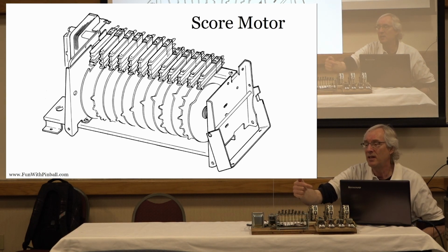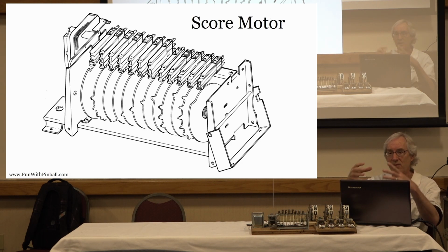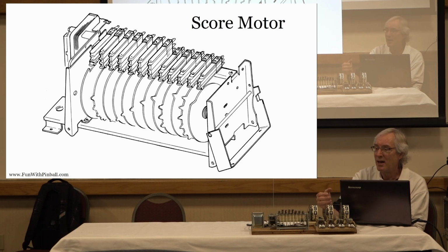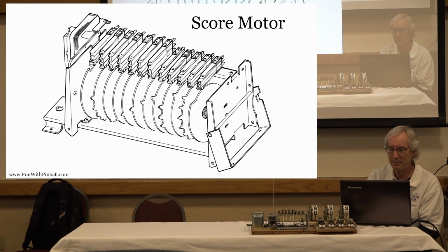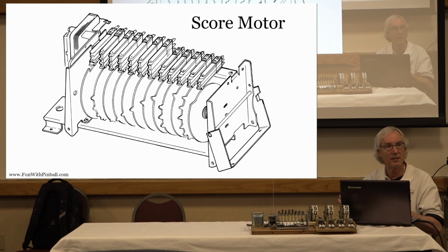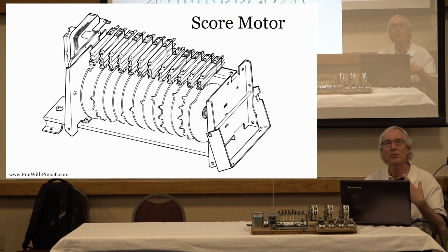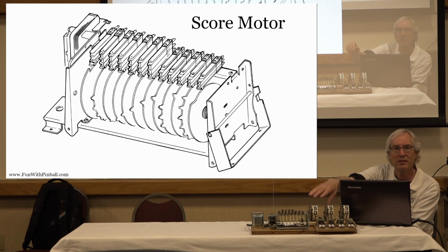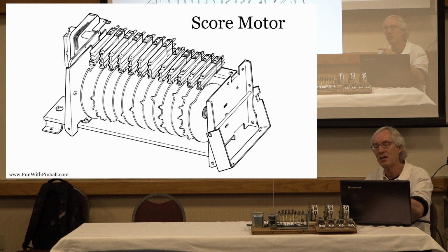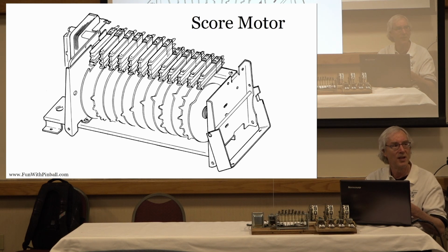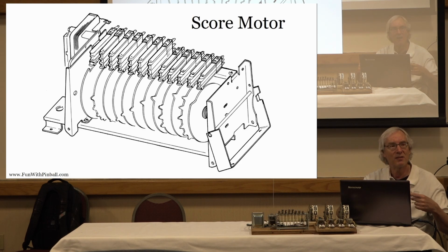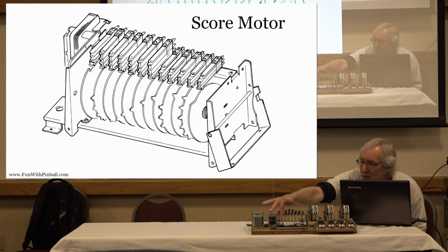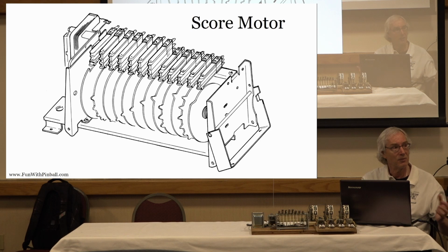And the motor knows that it has to run forward to the next home position. The motor can't just stop arbitrarily. It has to be ready for the next computation, the next bit of math. You may notice, for example, a lot of EM games have targets that say "lit," and that light will often go off when the motor is running. That's because the motor is committed to doing some calculation, and it can't start a second calculation until it has finished the first one. So it disables some of the more elaborate things on the game while it's doing the math to figure out what it owes you. And when it gets back to the next position, it's ready to start the next thing, whatever that is.